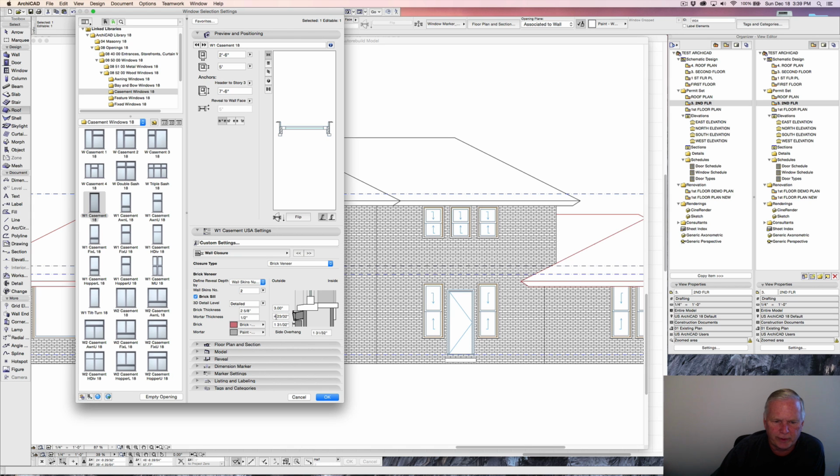This number here, 4 and 23 seconds, just goes in with a calculation for the overall thickness. I think we'll just make that 4 inches. And then this overhang, we'll make that 2 inches. Sometimes I think these numbers go in because they are ultimately derived from the European version, which is in the metric system, and they convert it, and that's how we get the 32nds or the 64ths or whatever shows up. So we'll just change that to make it something a little more in keeping with what we would have. And we'll look at our arch style.